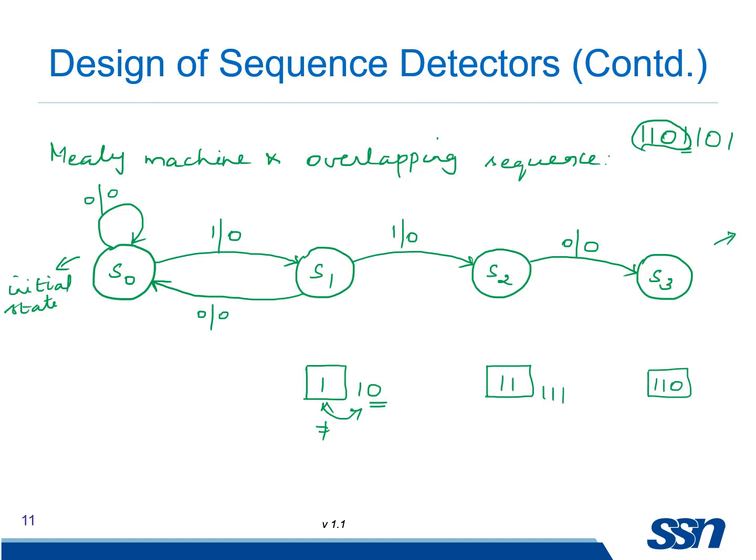If I receive a 1, we compare the last 2 bits with the 2-bit state. If this is equal, we remain in the same state. So 1, 0. Now coming to the last state. In the previous slide I have given the last state condition. So here we are expecting a 1-bit overlap. For 1-bit overlap, what we do is compare the last bit to the 1-bit state. That is, if we are to receive the final input as 0, we compare this with the 1-bit state, that is this one.